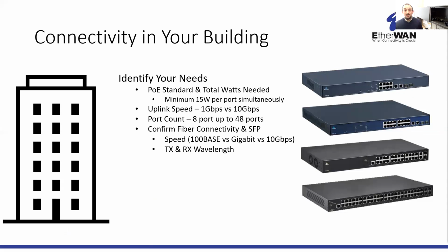Well, I definitely want you thinking EtherWAN for all of your hardened applications, but we can cover you on the inside too. So again, consider what PoE standard I need and what total wattage I need. This is really where, if you've dealt with IT switches, they really cop out and say, oh yeah, you can do 30 watts on any port, but it maybe only has enough total watts to do 15 on half the camera ports. Well, that's not going to be helpful in a security scenario. So all of our indoor commercial switches are rated at a minimum of 15 watts per port simultaneously. Many of the smaller form factor ones, like the 8-port, actually do 30 watts per port on every port.